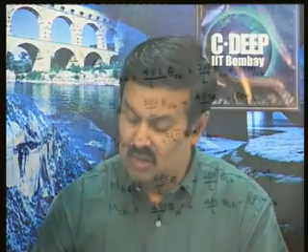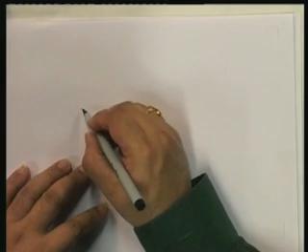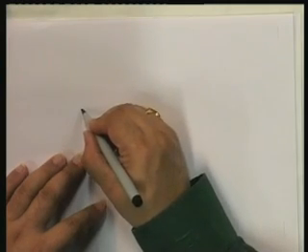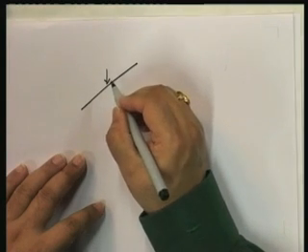Okay, what about fixed end moment at BC? Now that we have to find out. Okay, and let us find that out. So the next step is the fixed end moment at BC and CB, which is going to be there because in member BC there is a load in the member. So we have to find out what that is. And how do we find that out? Well, note that there is a slight difference here. The member is inclined, the loading is this way.